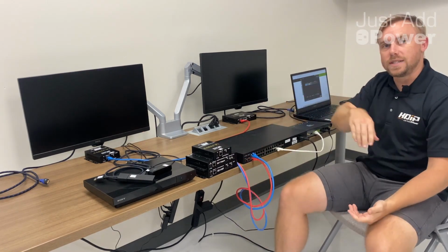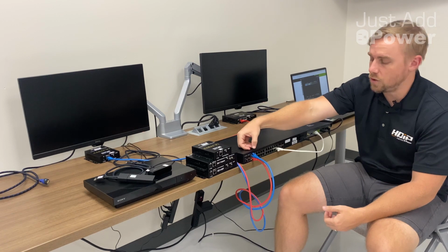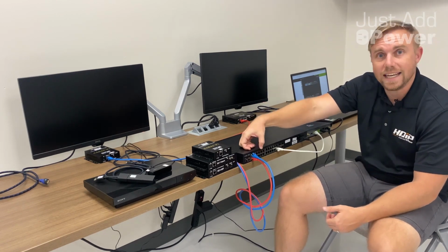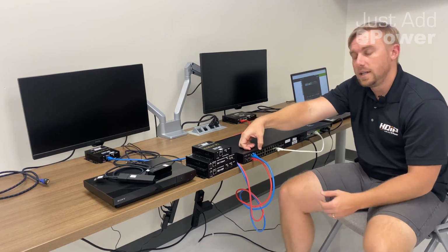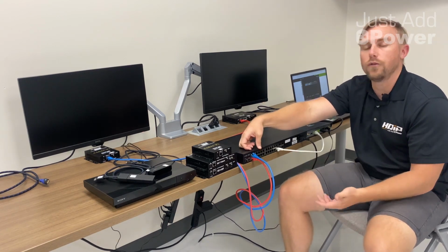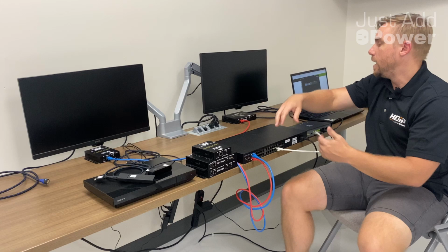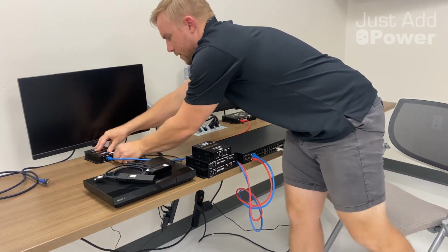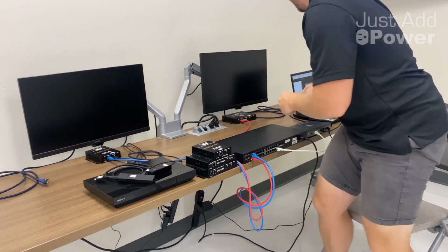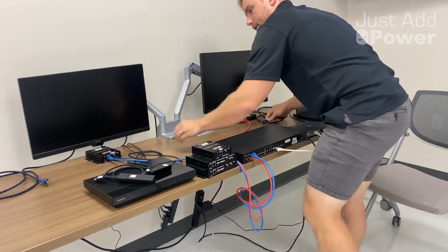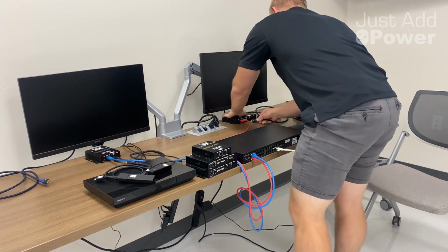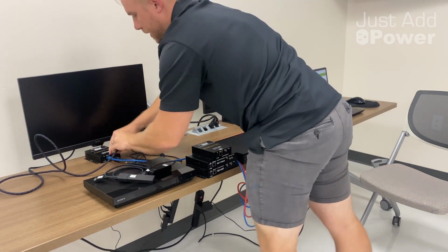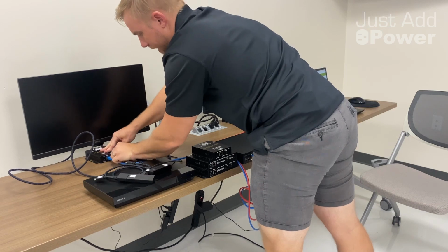If I had additional receivers, I would continue to connect them to ports 3, 4, 5, 6, 7, and 8. Because I don't, it's okay to leave them blank. Those are for future receivers. Also at this point, we're going to connect our televisions up to our receivers. If you wanted to connect HDMIs before, it's perfectly fine to connect the HDMIs beforehand.